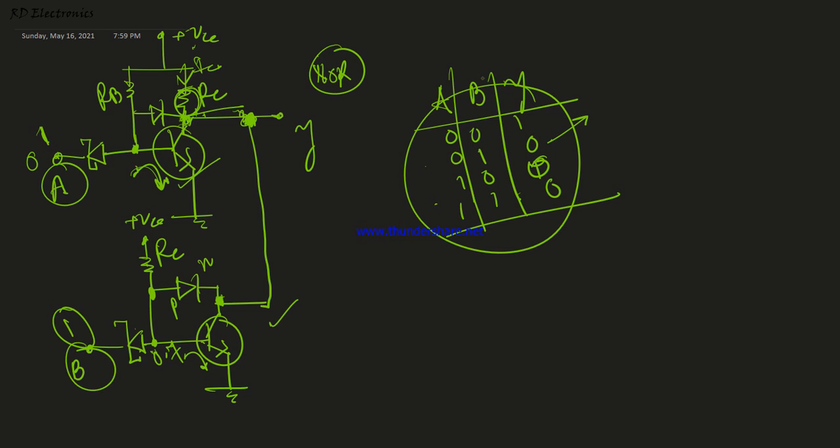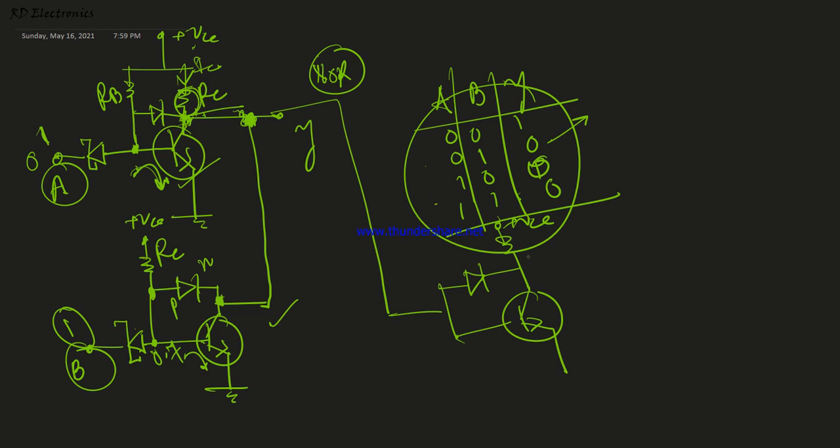Okay, so how can you design an OR gate? It's very simple. We just connect this output to this circuit. This is the NOR gate we already discussed in the previous slide. This is plus VC. This is an inverter. So from Y we get the A or B operation. This is our connection point. So this is our DTL technology using Schottky transistor, diode transistor methodologies.